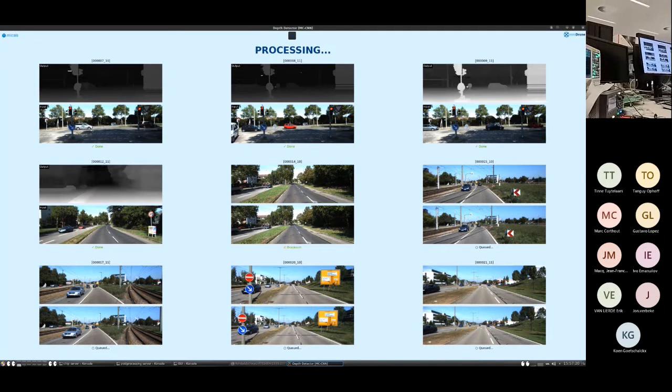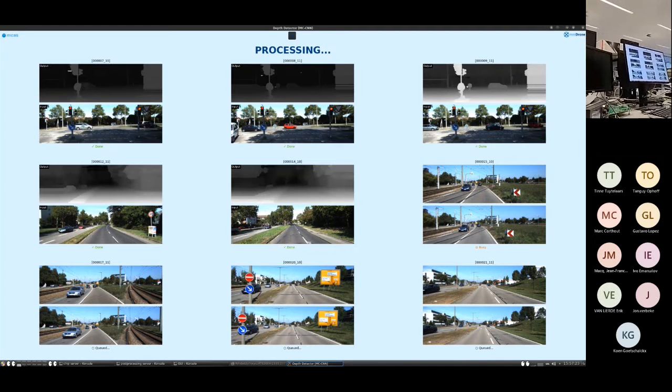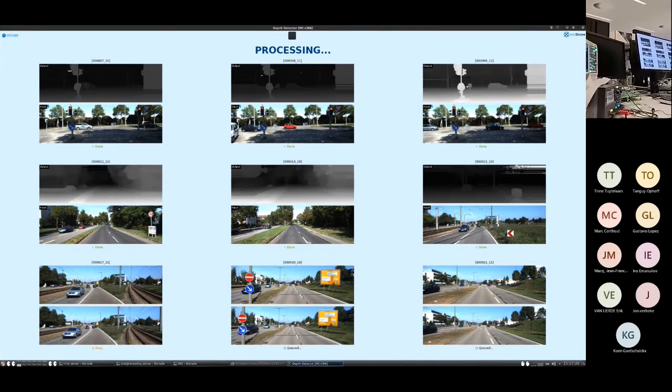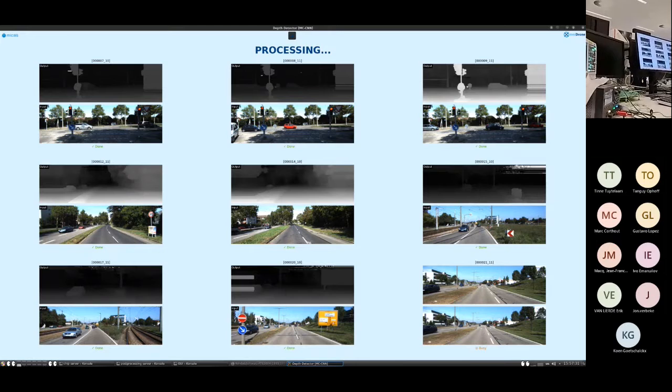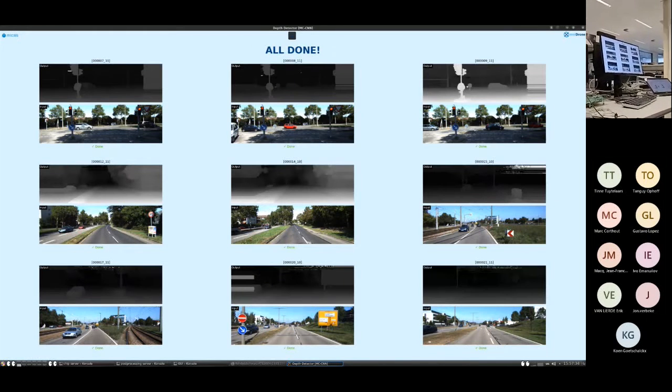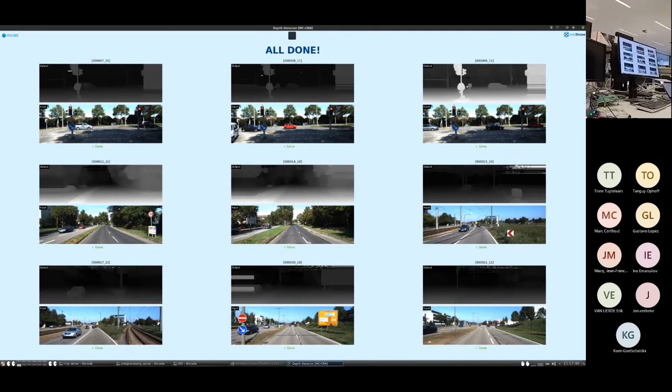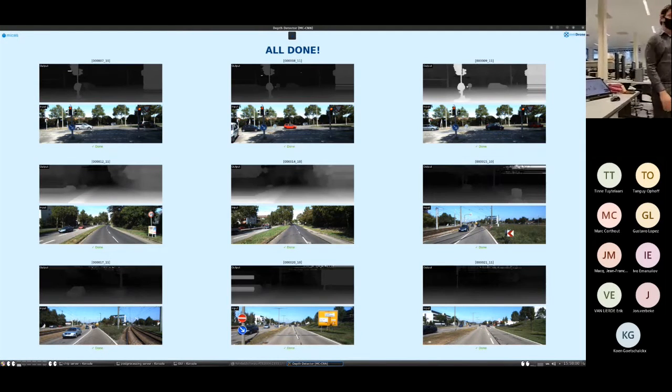What's important to note here is that due to our depth first approach, the actual I/O that we need, the thing that is so limiting to performance, both in energy as well as in latency, we compare to the I/O that is just the I/O of the network, so that's the bare minimum you can get, right? In the end, you do need to input and output, it's just temporary data that you want to avoid as much as possible. So the I/O of the actual network is the gray bar here, and the blue bar is what our solution, which is depth first, actually needs. So it's basically the same. While if we weren't doing this depth first approach, we would end up in this worse scenario where we do layer by layer. This is even assuming some best case assumptions, but you can already see it's about 6 times higher.